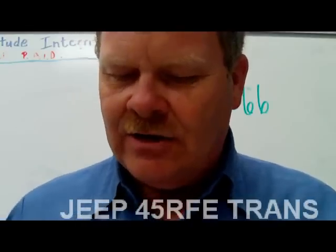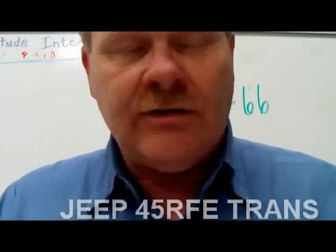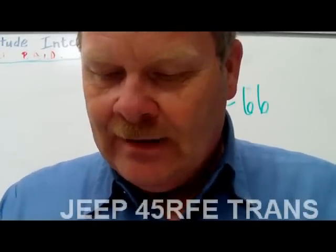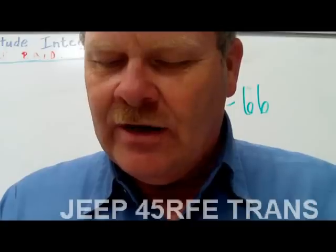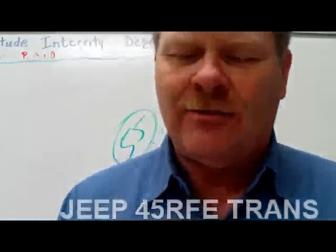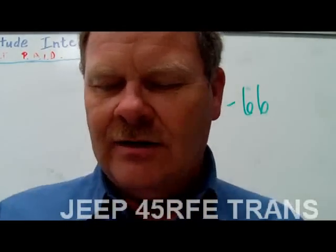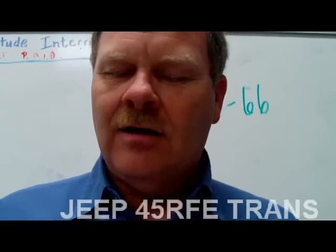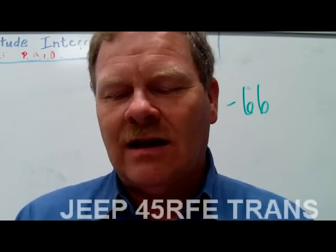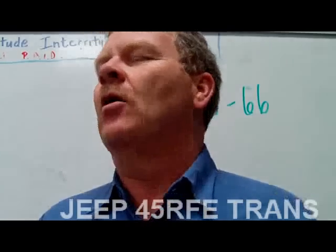It shows the different gear ratios: your 3 to 1 is in first, and reverse is 3 to 1. Second gear is 1.67 to 1. Now this other one, when you kick down, is what I'm trying to tell you. When it shifts up through its gears, first, second, it's going to go from 3 to 1 to 1.67 to 1. That's second gear. But when you kick down, it drops down to 1.5 to 1, which is another second gear ratio that's a little lower, and it's only used for passing gear. The only time it ever uses that one.